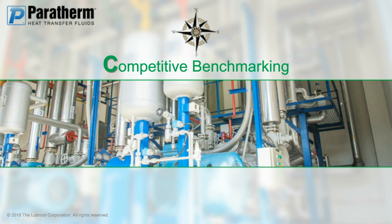And now based on that evaluation, you've decided on either A, a natural organic mineral oil-based chemistry that you're going to go with. It's going to give you great stability and performance, but it's going to be limited to temperature, but that's okay. Or B, you need to move to a higher temperature synthetic aromatic-based product. It's going to extend your range and give you higher thermal stability capability, but that's going to come along with trade-offs of greater initial investment and possibly some limitations on storage, shipping, waste removal, environmental issues.